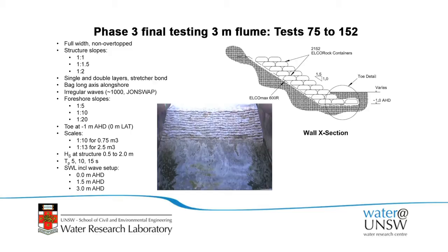If you're into water levels, you'll know the open coast water levels on the Australian east coast, that's about your 1 in 100 year level, 1.5 metres AHD, but realise we're inside the surf zone, so we have wave setup on top of that. So this is a wave setup level inside the surf zone, and that pretty much represents about the highest wave setup level you'll get inside the surf zone anywhere on the east coast of Australia. You could theoretically get a 10 metre wave, which would give you 1.5 metres wave setup on top of your 1.5 metre water level. So that's 3 metre AHD water levels, pretty much an upper limit for anywhere open coast, east coast Australia. Wave run up still goes above that as well.